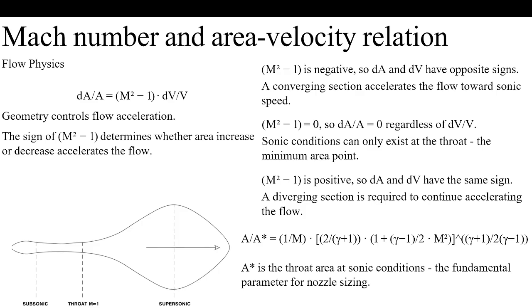When it is equal to 0, which implies the throat, your Mach number will become 1. At that throat, the minimum area, as I already told, the throat is the condition where the area of your nozzle is minimum and the Mach number is coming to be 1. That condition is called a choked nozzle, which I will be explaining in the next slide.